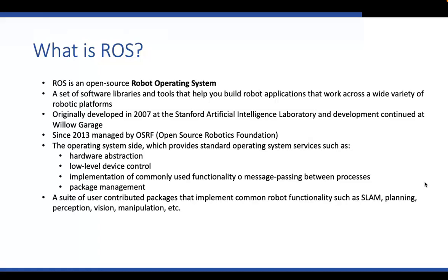Then you can always write packages, and you should try to write them as modular as possible. For example, you write a package just for generalized object detection and use it in one project. Then you have another robot, say your first robot is for an industrial project, and now you want to use this object detection model in a human-collaborative environment. You just take this package, install it there, and use it. That's why ROS is very advantageous in that context.